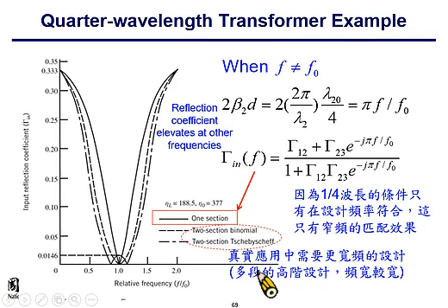In between, the reflection coefficient will rise a little bit, but as long as it's smaller than your specified reflection coefficient magnitude, you should be safe with this design. This is just two-section binomial, so the broadening in bandwidth is visible, but not that obvious.